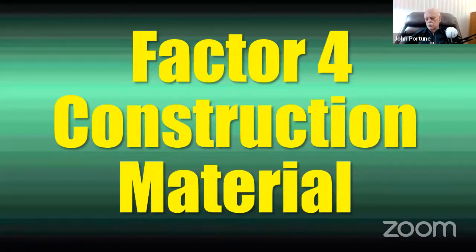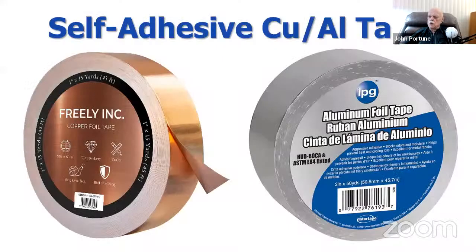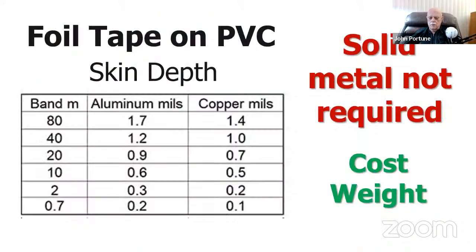All right, number 4. To me, this is another biggie. This is my favorite. Construction material. As you well know, I'm a fan of metal foil tape, copper and aluminum foil tape. And the reason I am is because of its skin effect properties. Here's the skin depth. And you can see it's very thin. Copper, 1.4 mils, 1.4 thousandths of an inch at 80 meters, and 1/10 of a thousandth of an inch at 70 centimeters. And in aluminum, it's also thin too.